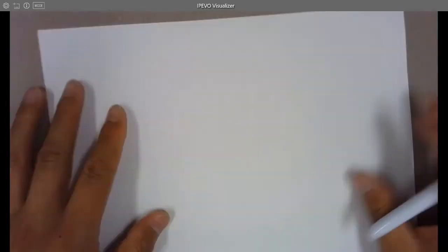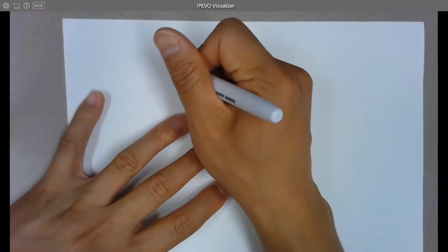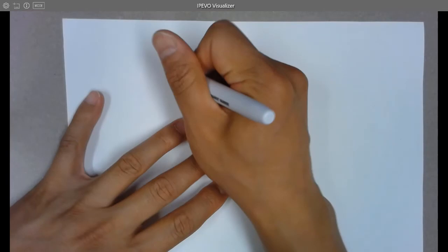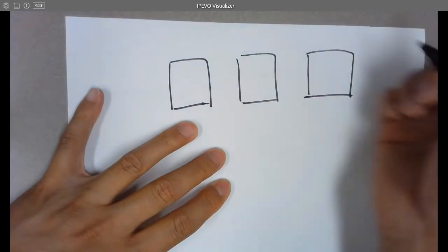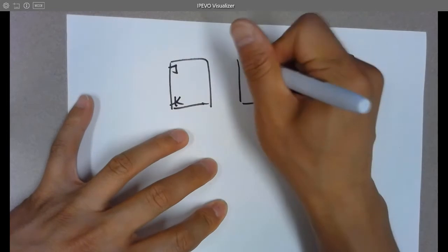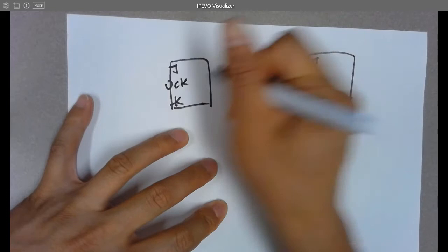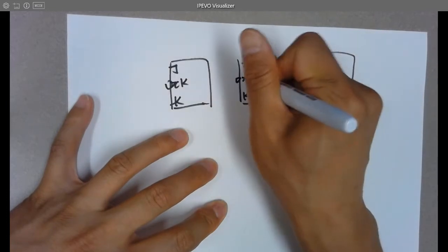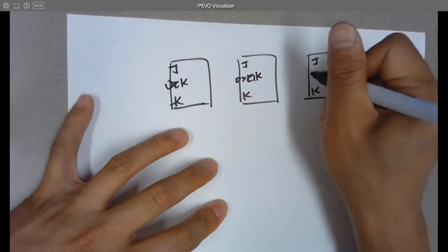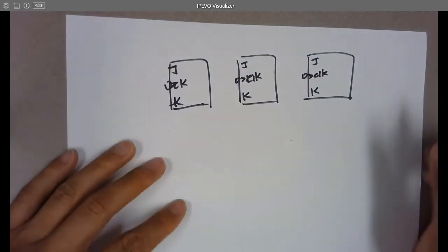So you can actually stack them together to make more bits for that flip-flop. For example, you can have this one here, here. That's a 3-bit, right? You can add more, but I just show you this as an example so you know how to do it. JK, JK, JK flip-flops, and all of them are falling edge triggered flip-flops.